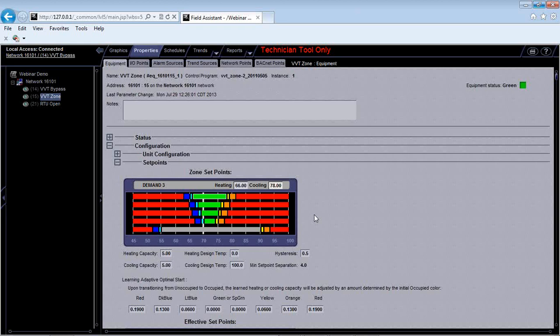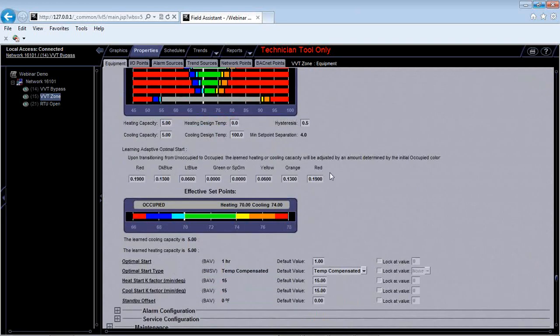It's just a matter of you need to have some sort of power measuring system on the network that can read the peak loads and then tell this controller when it needs to go into demand limit 1, demand limit 2, demand limit 3. But it's a great feature for energy savings. It's just a matter of you need to have the required parts on here to do that, which would be power metering. So if I continue down, you shouldn't have to worry about any of the configurations below that.